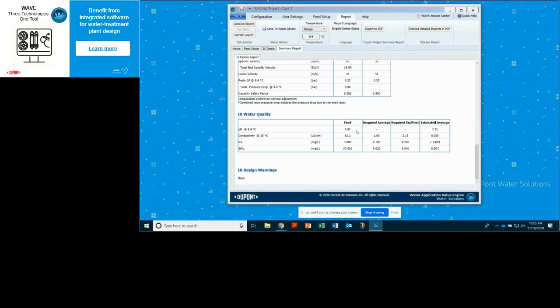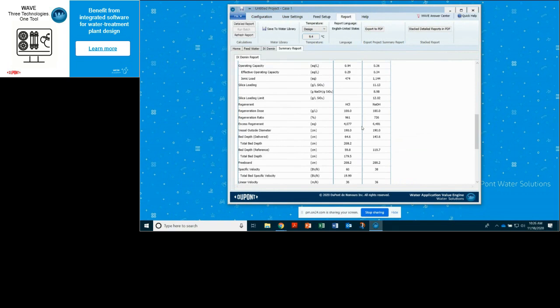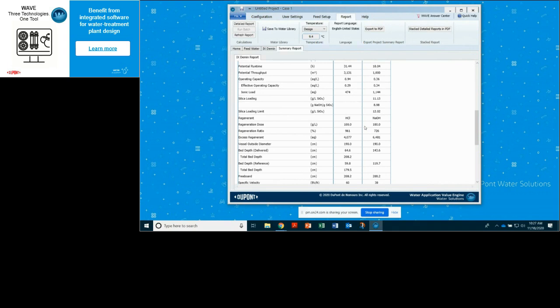Okay, Donna, do you have any other questions about our working mixed bed? I think we had a question that came in from the audience about resin selection and why the 1200 and not the 1300. So our 1200 is about 8% DVB, and traditionally in mixed beds we had used the 1300 because it had a nice contrast in color between the anion, and the 1200 now is an improved version and is darker, so we can now use it.